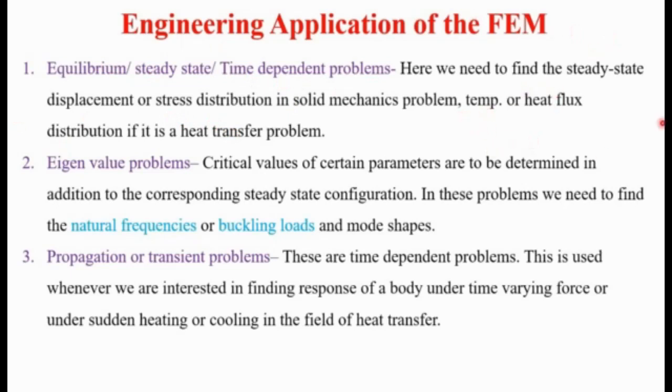Then, to get the temperature value or heat flux distribution in a heat transfer problem, or pressure distribution in a fluid problem, in such time dependent applications the finite element method can be used. Then in eigenvalue problems, we calculate some critical values of certain parameters, in addition to the corresponding steady state configuration. In these problems, we need to find the natural frequencies, buckling loads and mode shapes in solid mechanics problems. That means along with the displacement or stress distribution, if we want to calculate the natural frequencies, buckling loads, or mode shapes, in such eigenvalue problems the finite element method can be used.